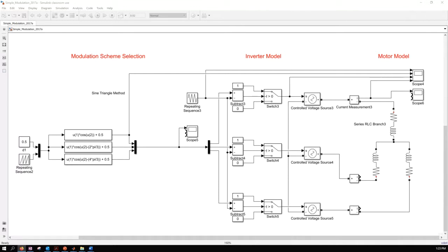In a closed loop system where we have field orientation, this is our position signal, and we base the voltage that we apply on that position signal, because we want to align how we apply the voltages so that the currents are aligned to generate optimal torque, right? We have discussed this in previous discussions.